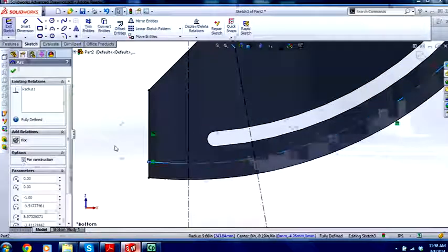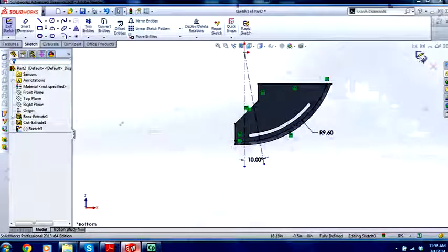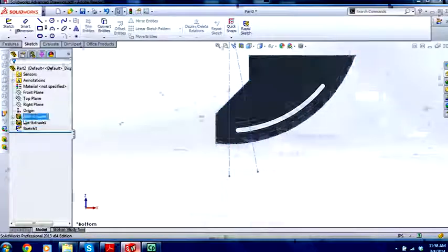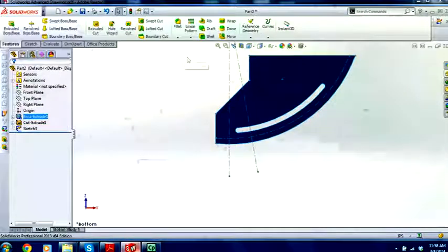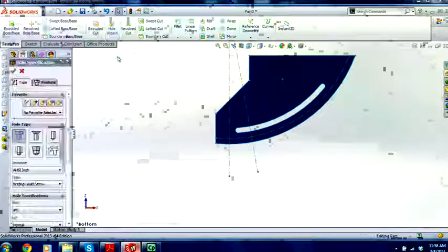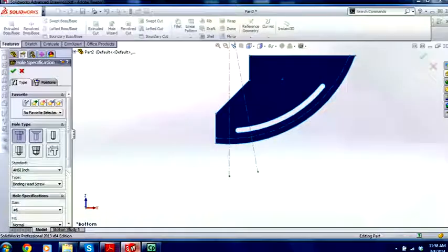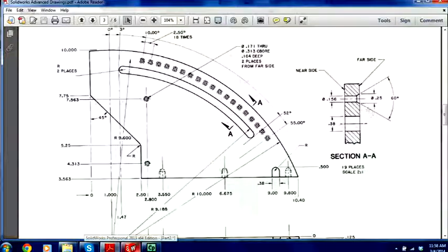That's the first point of the countersink. So let's make that for construction, and let's just get out of here for a second, and leave that sketch on. I'm going to click on this face. I'm going to go hole wizard, and I want a countersink hole. Now what is it? It's 60 degrees, so it's some crazy one.